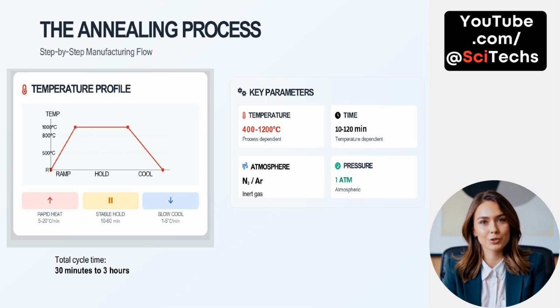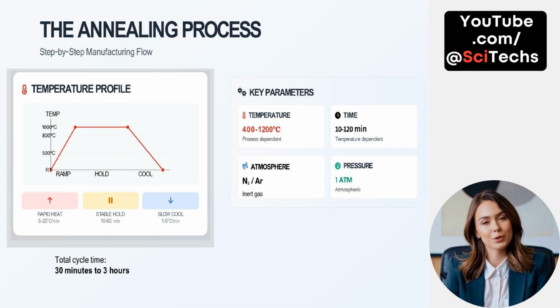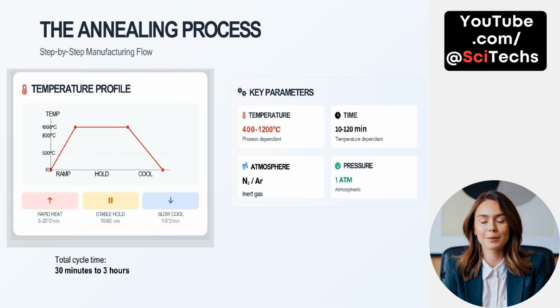Temperature is one of the most critical, typically ranging from 400 degrees Celsius to 1200 degrees Celsius, depending on the materials and desired outcomes, such as dopant activation or defect repair. The time for annealing also varies with temperature, usually lasting between 10 and 120 minutes. Shorter times are used for high-temperature anneals, while longer durations apply at lower temperatures to ensure uniform thermal diffusion.